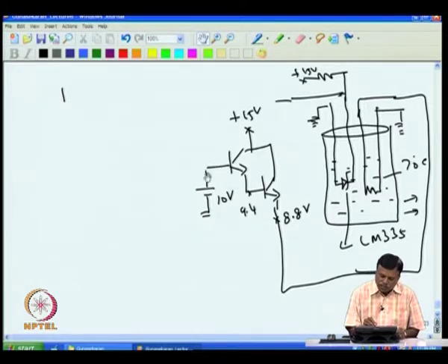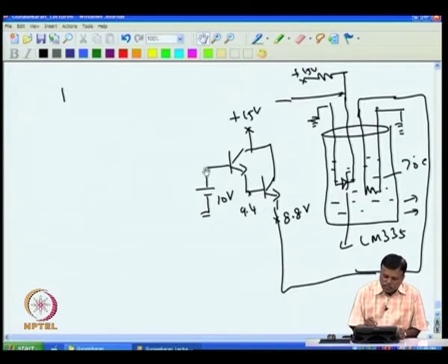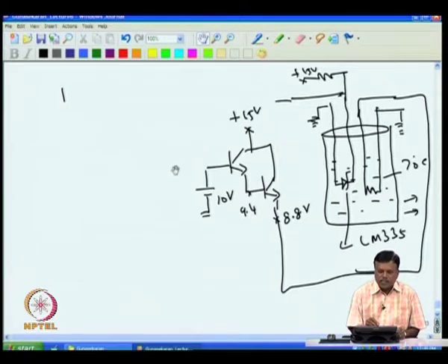So, here 1 milliampere current will be flowing, whereas here 5 ampere current will be flowing. To boost the beta only, we have done this Darlington pair arrangement. The advantage is that now I need only a very small base current. If I apply a small base current, it is multiplied by beta times and the current comes. So, my controlling device, which is going to be the operational amplifier here, need not give high current. That is why this arrangement is made to drive the heater.